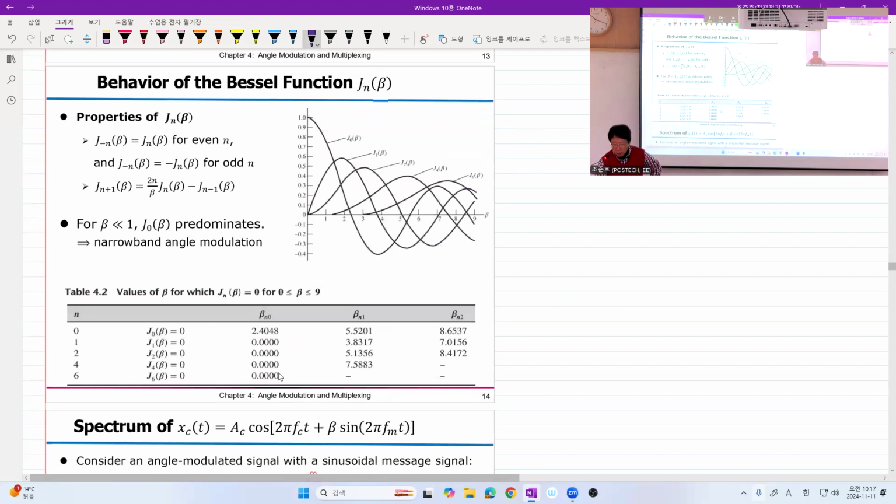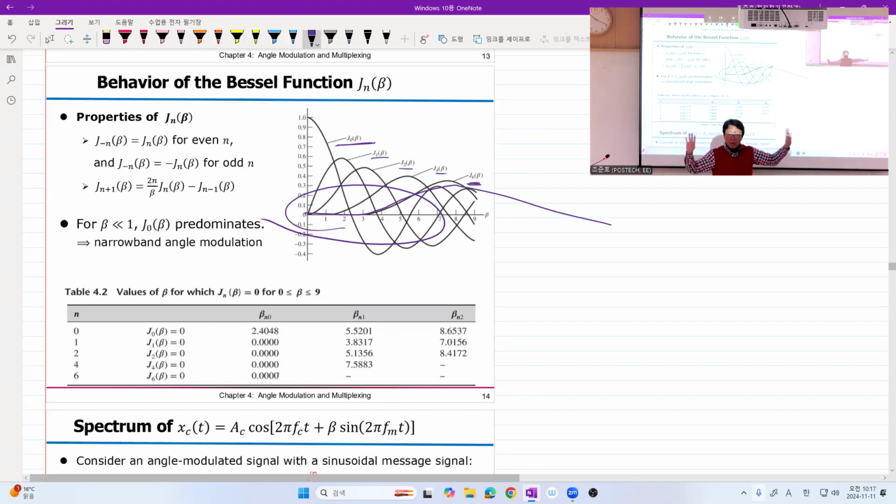And here, except the zeroth term, the DC term, all the other terms have something interesting. Of course, if the argument here, beta, increases, there is a trend that you have smaller and smaller values. However, for the large order, it starts slowly and then decreases. What does that mean? High order harmonics are much more affected by this small value of beta. So FM actually has a more confined bandwidth in some range if you carefully choose this proportionality constant.